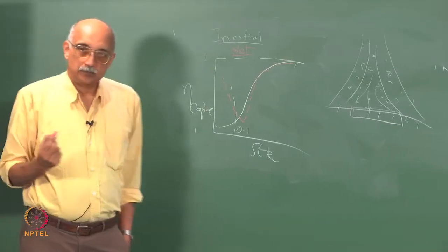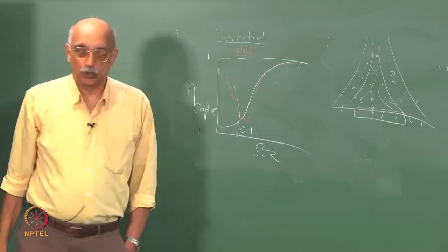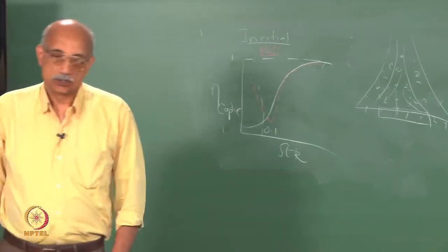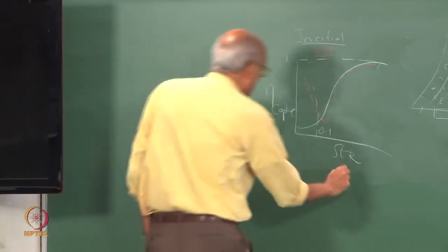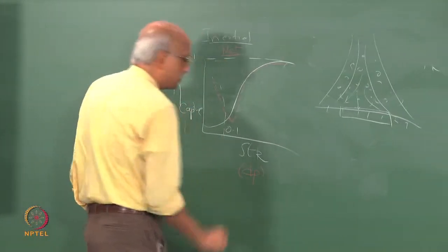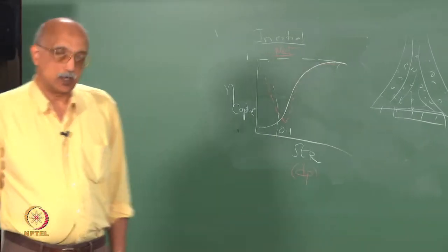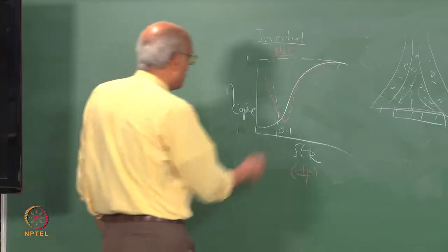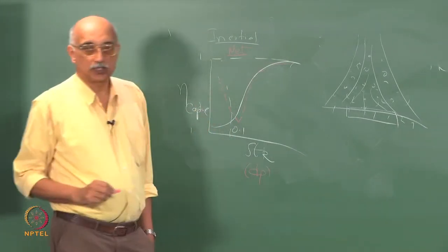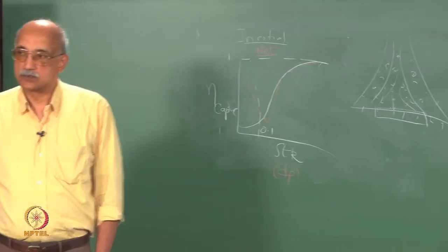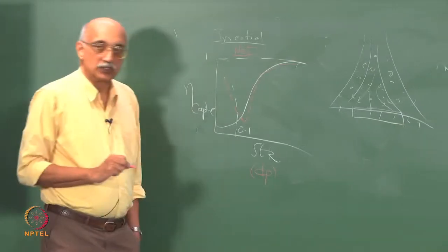What is the reason for that? The reason, of course, is that at extremely low Stokes number values, diffusion starts to dominate. In a sense, you can substitute dP here for Stokes number because the two correlate pretty well. So, as particle size decreases, even though inertial impaction effects are decreasing, diffusional and electrostatic effects start to increase, and so you will get a higher capture efficiency.